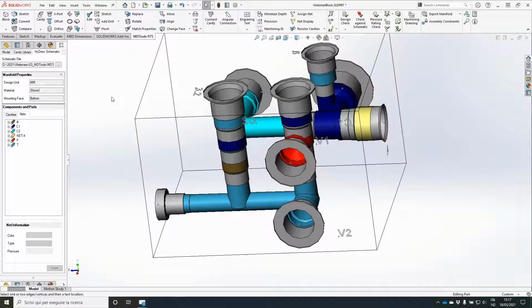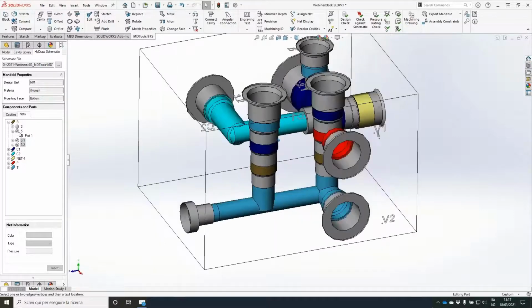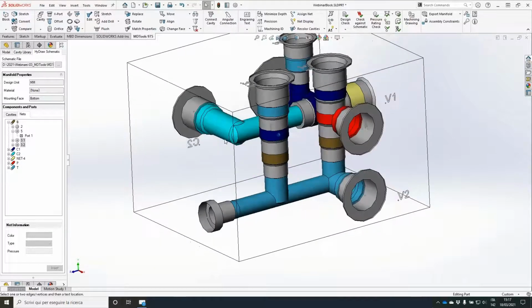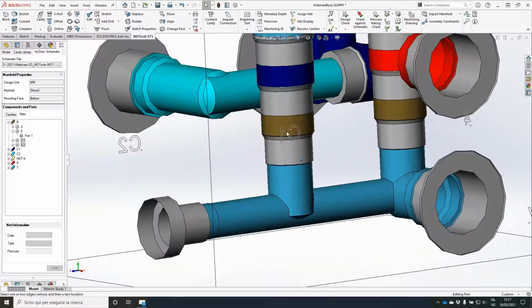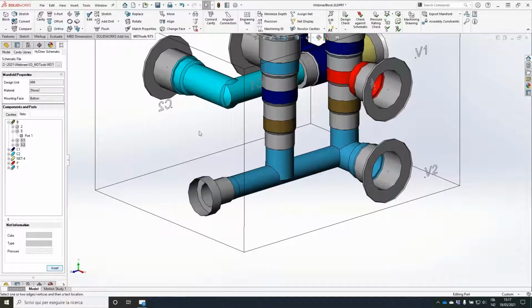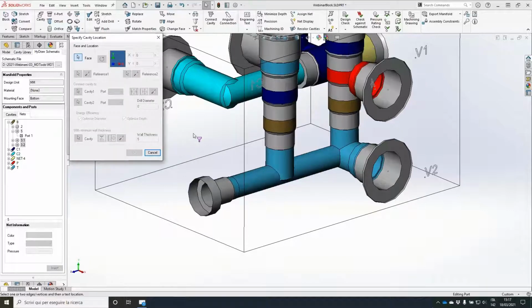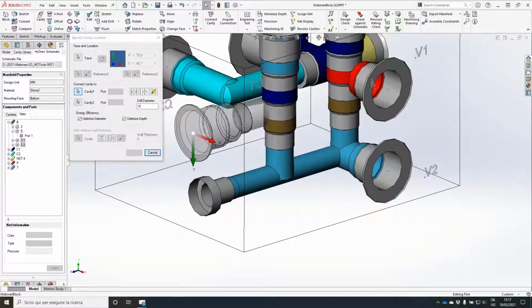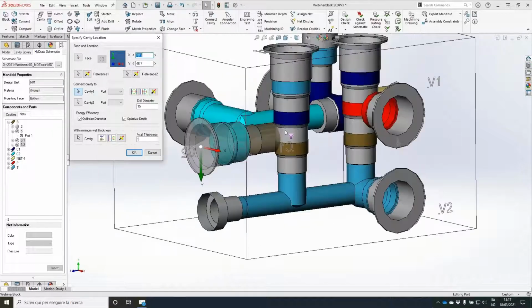Let's go back by net. So a different approach, instead of just taking the cavities and placing them and understanding how they are connected by looking at the colors, we can really expand the net and see which cavities are belonging to each net. So for instance, here we see the net B with this dark green, we can just insert the cavity and place it here, and we could make maybe a connection, but I don't really like this position.